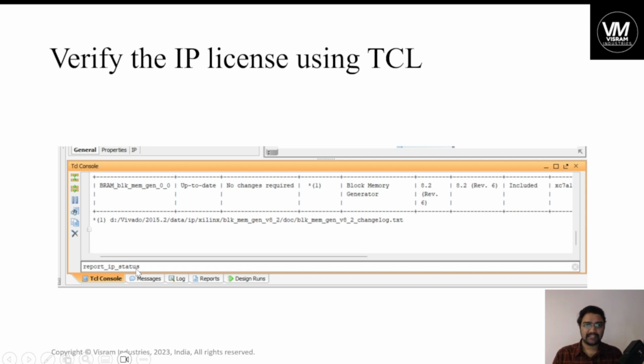And also we check the static timing analysis, that is the timing part. So these Tcl scripting, or you also might have heard about Perl scripting, those are in the design tools in the chip designs. So go to these and search for what these applications are. And the simple explanation is: give the command and make the EDA tool design your chip and verify this chip's functionality, again with the Tcl commands.